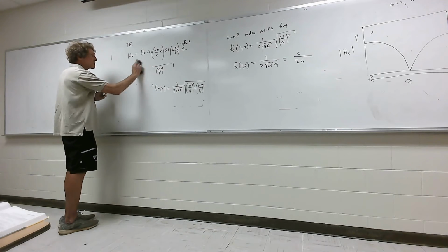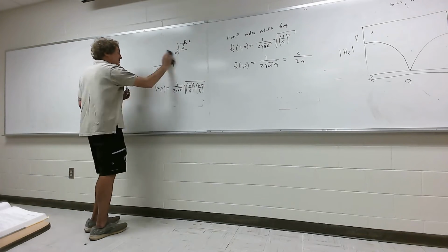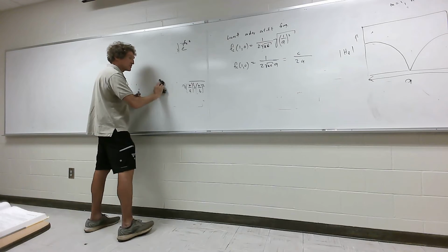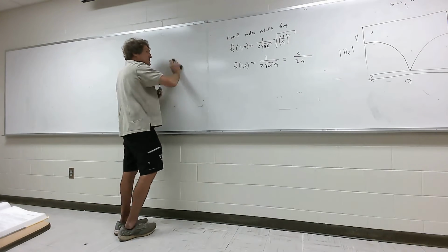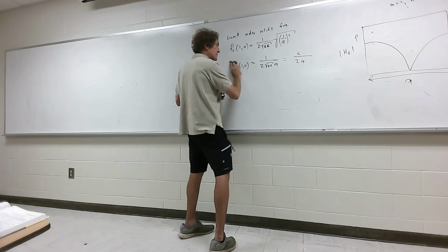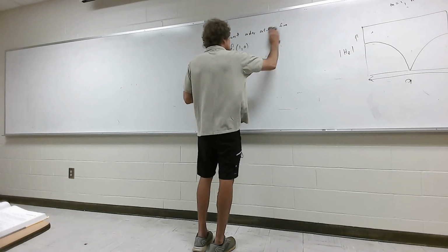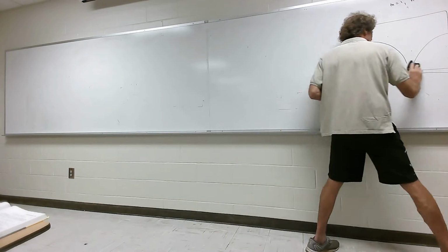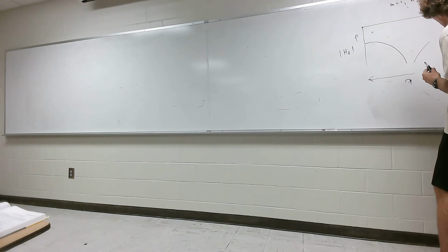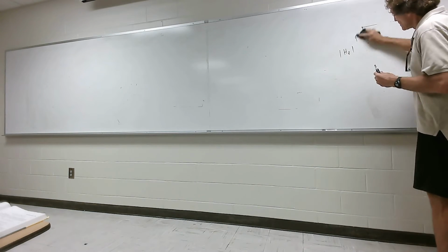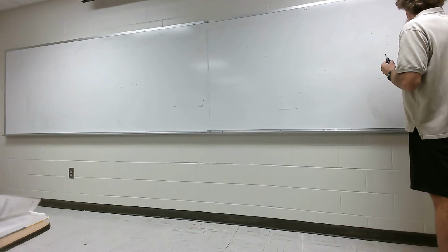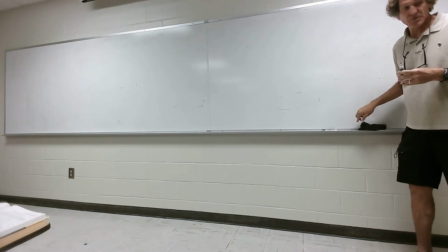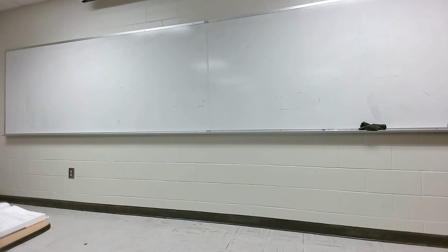Normally speaking, you don't ever want to do that. I don't know of a condition where they do it. With circular guides, it's a little different, but we don't actually solve the equation for the circular guide. If we had a circular waveguide installed, you'd find the dominant mode will actually be a TM mode. But I'm not going to do that, because your book doesn't touch it, since it requires Bessel functions.